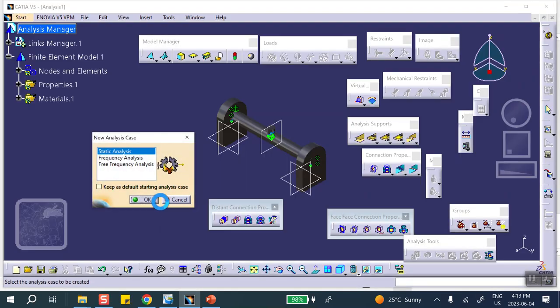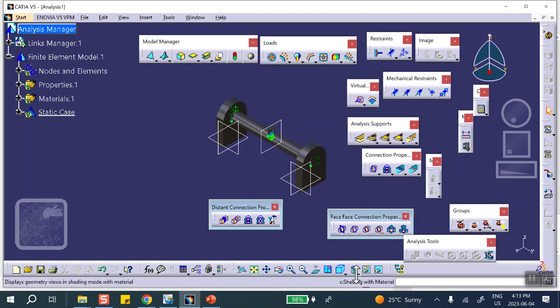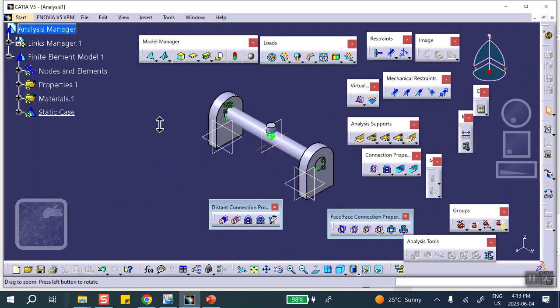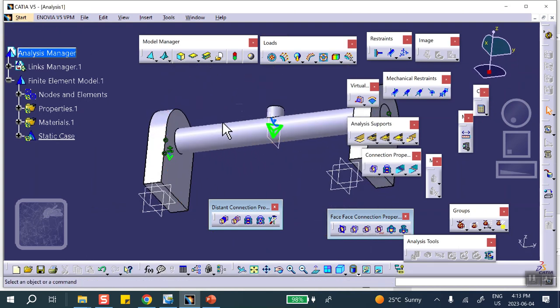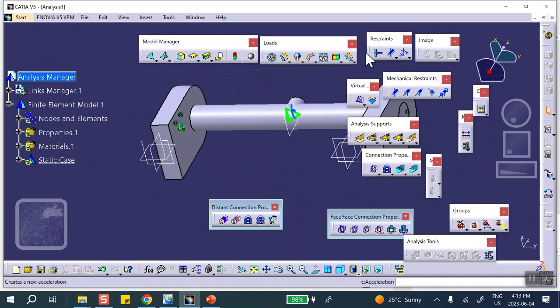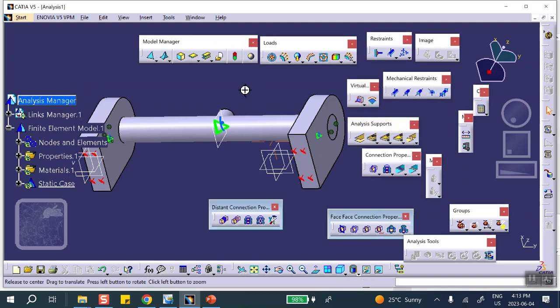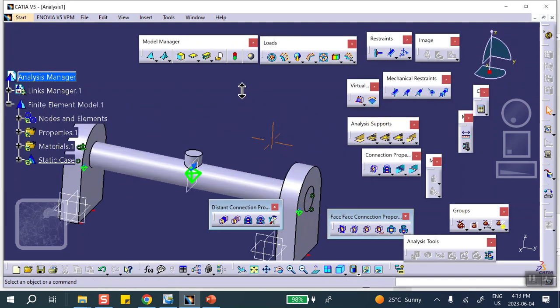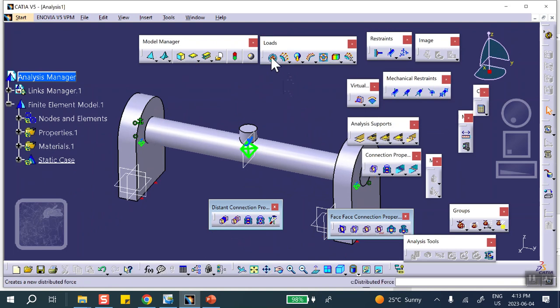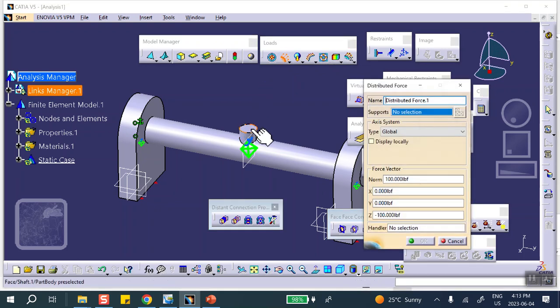No planes of symmetry are used, remember? Deactivate the plot. No, what I mean is change the rendering. The bottoms are clamped. This is clamped, and this is clamped. You put a pressure on the top, or some kind of a force on the top. Remember, if you're using symmetry, make sure that you appropriately divide that by the appropriate number. Let's say, I don't know, maybe 100 pounds, I'll put 1,000 pounds.